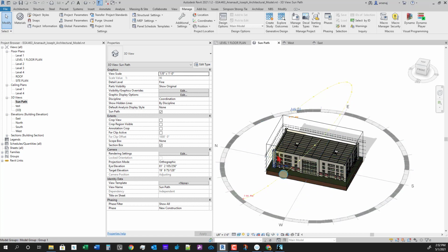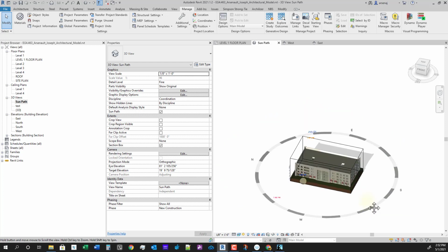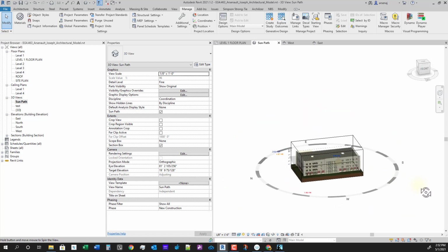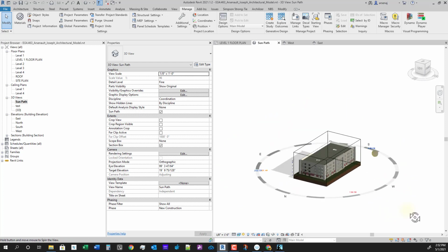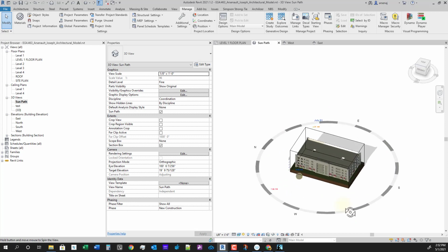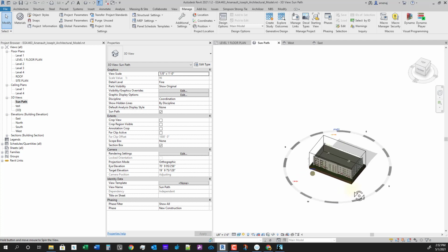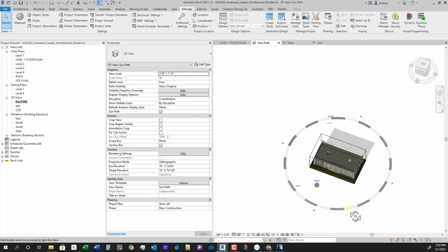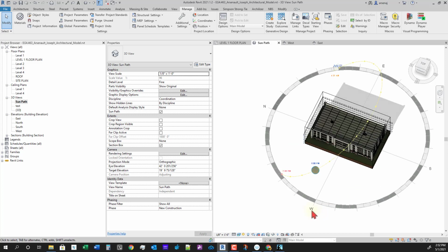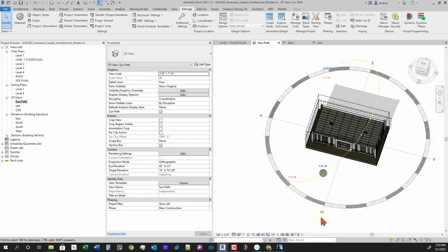So you'd probably want to add canopies over here as well, since it's going to get a large portion of the sun, most of the day. That's a cool and pretty useful feature for designers to be able to see in real time, based on a real location, the effect the sun is going to have on their building. And as you can see, when we turned it on, it knows that we rotated our view so that it knows the west is down here.